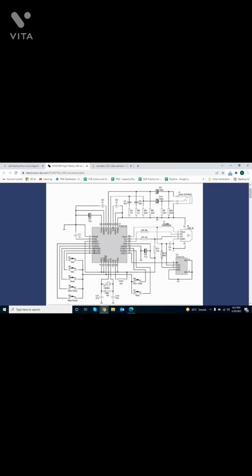Between pin number 16 and pin number 15, there is a 1.5 kilo ohm resistor for internal IC preparation. Pin number 32 is connected to ground via a 47 microfarad capacitor, pin number 2 is connected through 1 microfarad to ground, and pin number 1 is ground. And pin number 30 is connected to another capacitor, a non-electrolytic 1 microfarad capacitor, to ground for internal filtering.